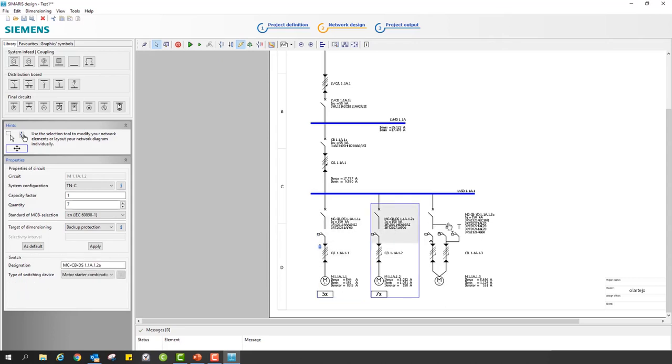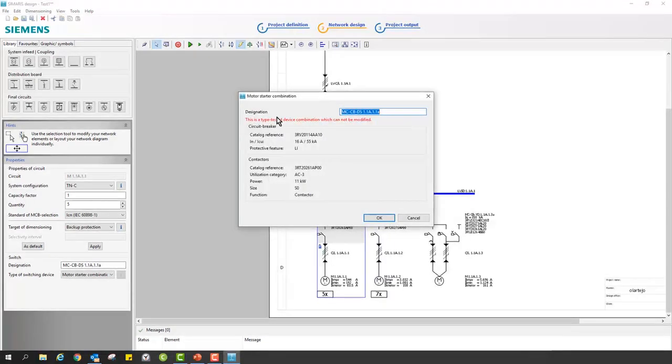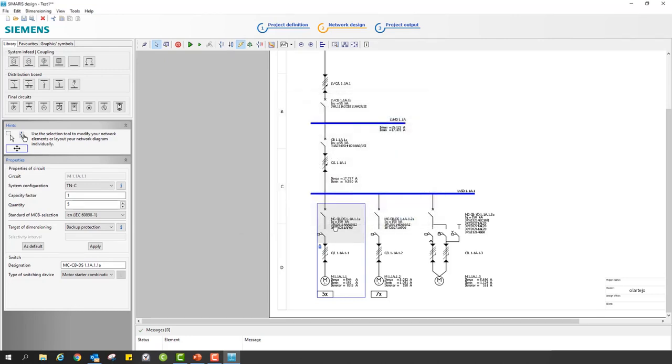Now, what happens once again if I bring it to 4 as it was, and again, I put in an even bigger cable. Remember it was 50 meters at the start and I had 1000? Look, now when I have 100 meters, I actually have only 500 amps as the maximum short circuit current. Why is this locked here? Because I've made some changes for the starting of the dimensioning.